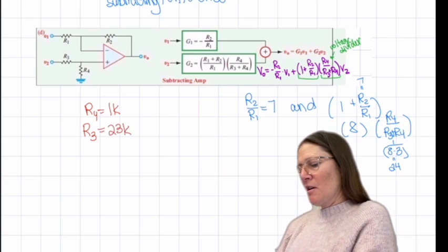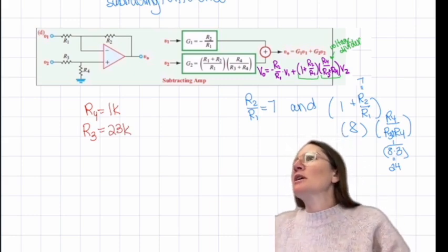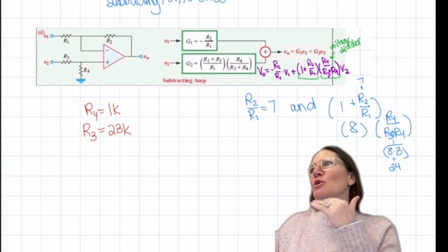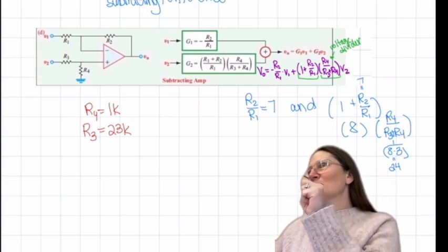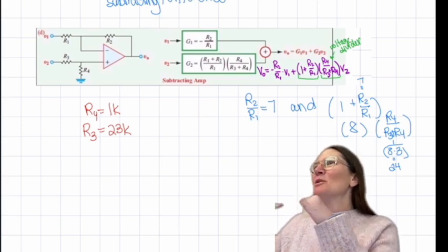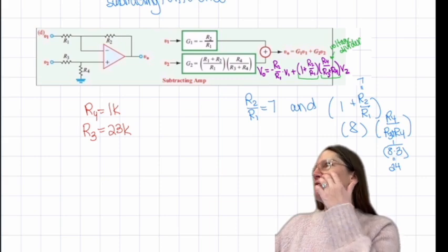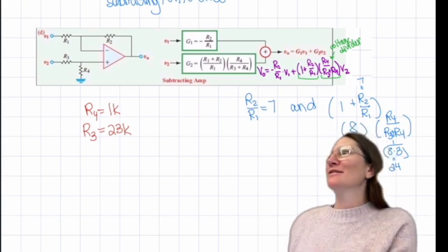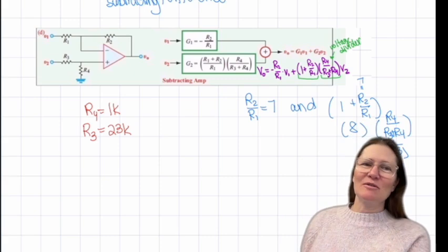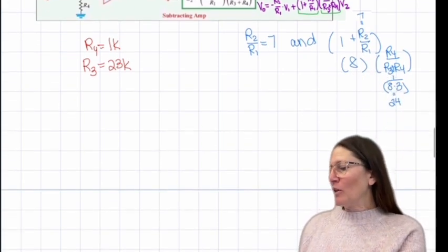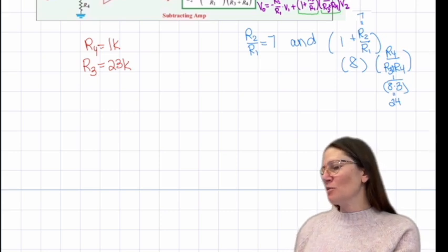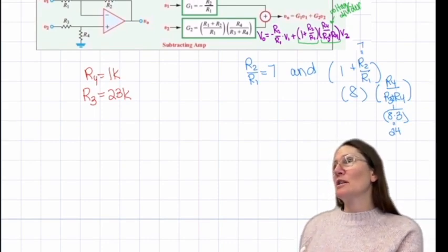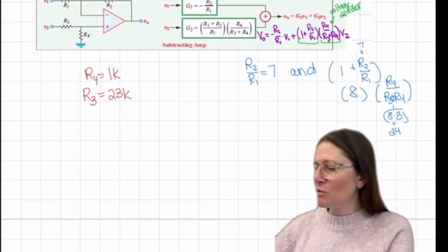The reason I use K is because if you use ohms and really small values, usually when you have currents drawing through them, that's going to be so small it will heat up. And so typically in designs, you want them to be in the K range. That's why I'm always putting down like 1K instead of 1 or 10 or 100, because 1's easier to divide by 2. Okay, so this would give 1K on the top and then 24K on the bottom. Multiplying that by 8, that would give you that result, correct? So then what could you do for R2 and R1?